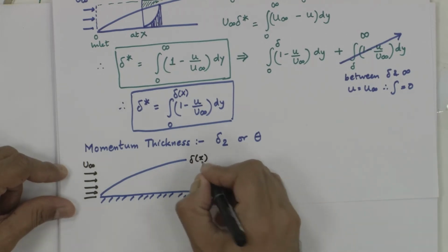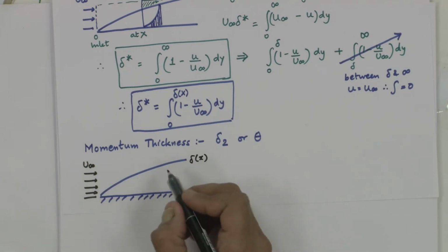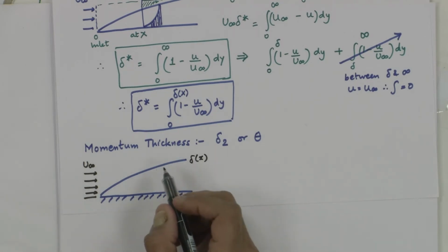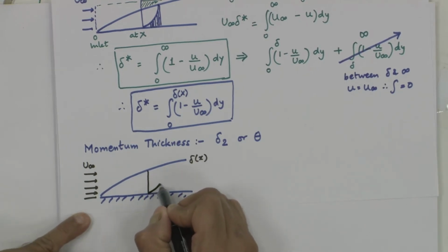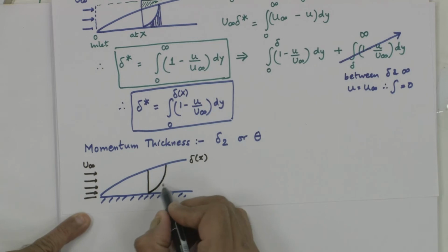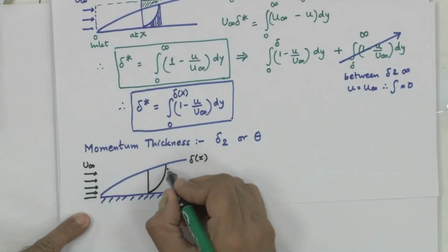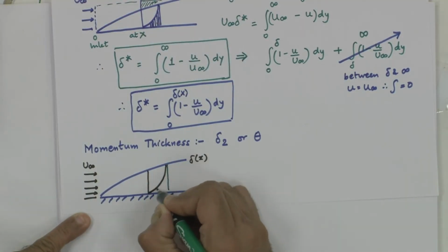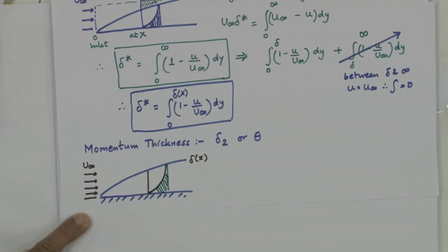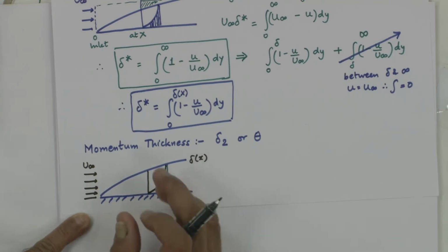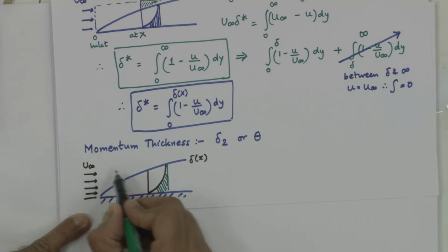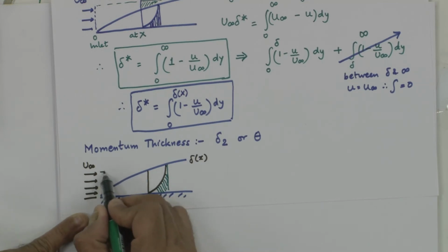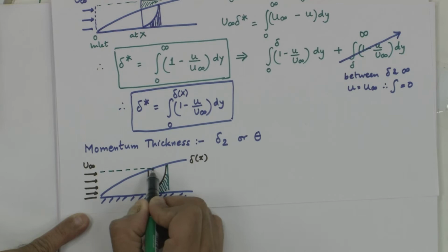When the fluid exits a control volume, part of which is in the boundary layer, the mass that is being carried out at that location is obviously lower than what came in because of this velocity profile. So, the momentum that the fluid is carrying out, if I look at a control volume, which let us say is given by this one, the green one, is my control volume.